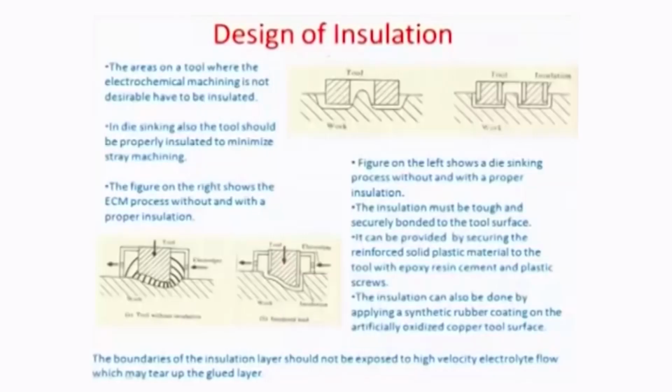The other issue which needs to be considered for ECM is how to develop good insulation on the tool, and there are a good number of reasons for developing insulation. For example, let us say this figure here considers a completely non-insulated tool. So, there would be ECM carried out between the tool and the workpiece in this direction, which is what we need or what is intended, but then also there would be ECM carried out between the sides of the tool and the workpiece.